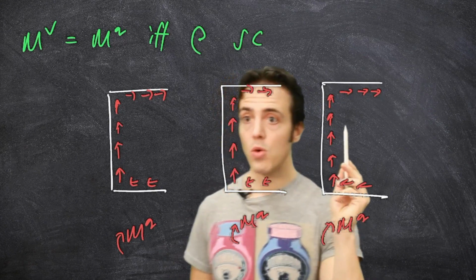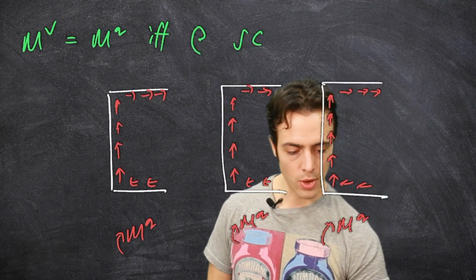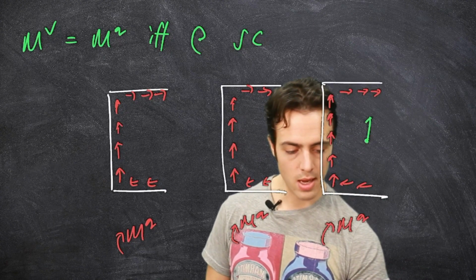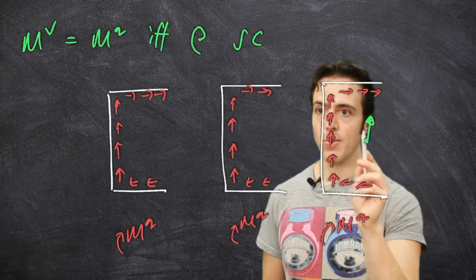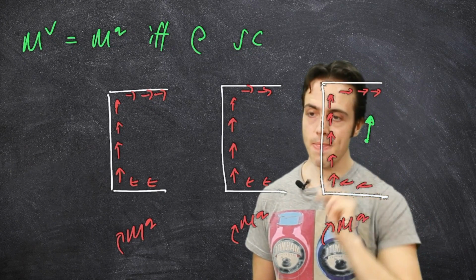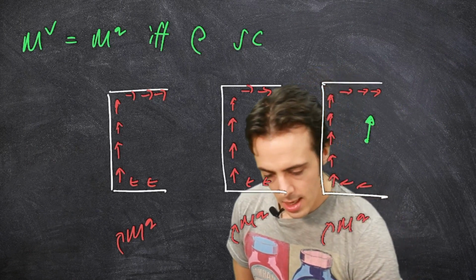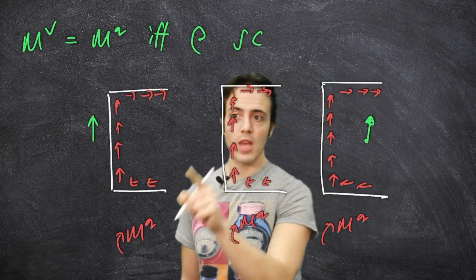Then that means we cannot load, for example, here, because no matter where I evaluate a moment here, I'm always going to get a counterclockwise moment due to this part here. If I load outside of the section somewhere, I'll get a moment in the same direction.